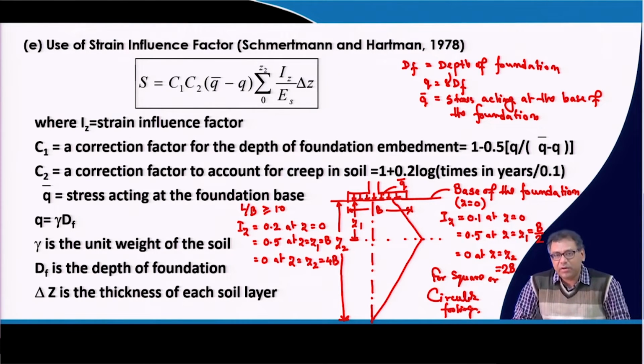But in general, for any type of footing, you can consider an influence zone up to twice b for other problems like consolidation problems or the methods that I have discussed, where the influence zone is required. So, in this particular case you consider 4b for strip footing, but twice b for square and circular footing. For other problems you consider the influence zone as twice b for the settlement calculation and b for the bearing capacity calculation.